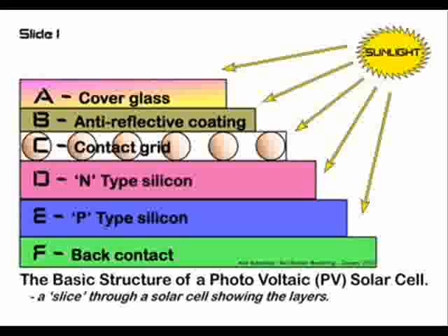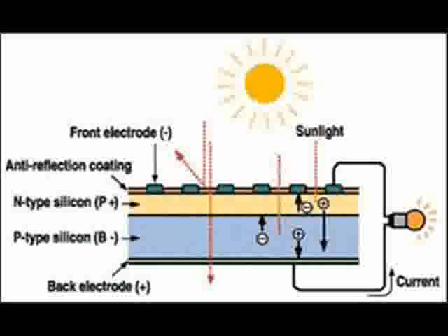An anti-reflective coating is spread onto the front surface to cut down on reflected light. Finally, front surface contacts are made to collect the electrons arriving from the junction. The grid is constructed with as few contacts as possible so that the p-n junction is not shadowed too much. We can now power a light bulb or an electric motor by completing the circuit. Now the cell is complete.